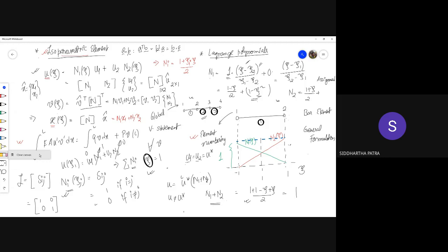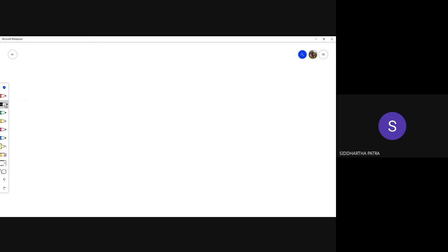So let's now move into the solution. Now we have seen the variational. What more do we need? We need to express strain. Strain is u prime, which is du dx, which could be written as du d xi times d xi dx.